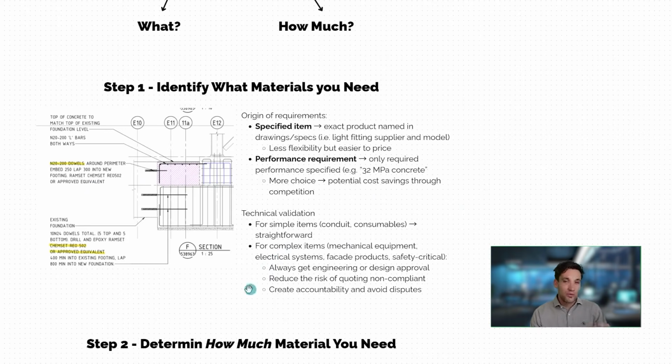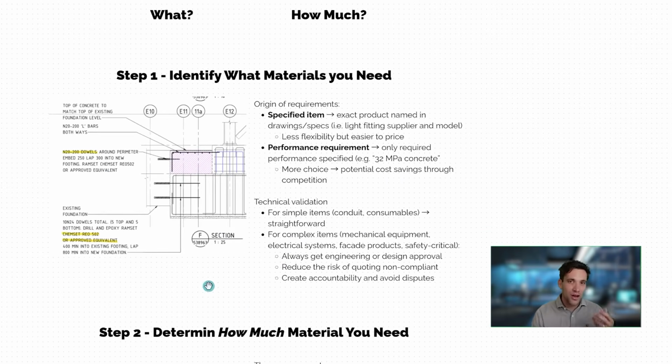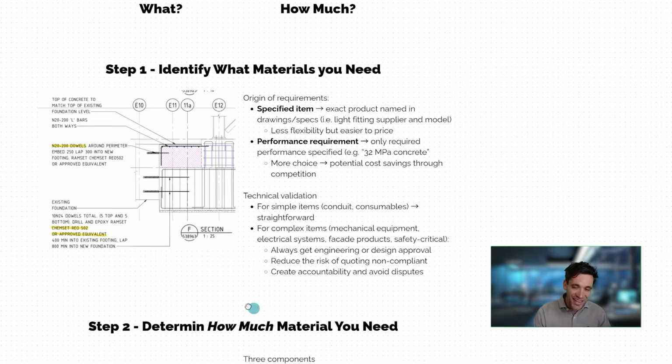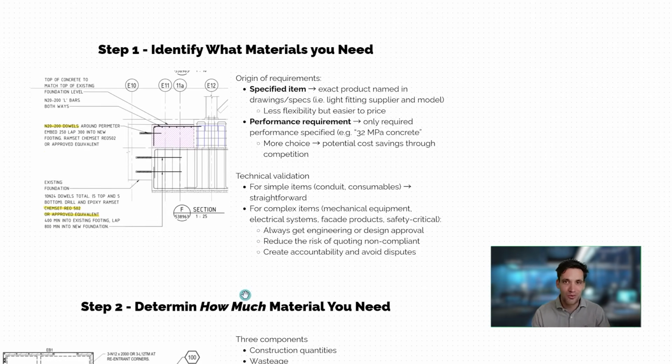So one important qualification as well is because we're pricing materials during pre-construction, the challenge will be that we probably won't have enough time to get the product approved for use by our clients or the designer. So in practice, while during a construction project, you've got more time to go through the whole process of getting and vetting quotes, getting product specifications approved, during the tendering phase, you probably won't be able to engage a designer, or your client probably won't respond to you if you ask them to approve the products you're using.